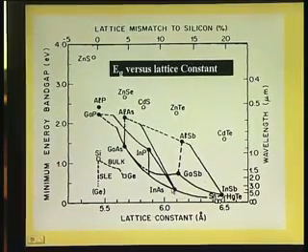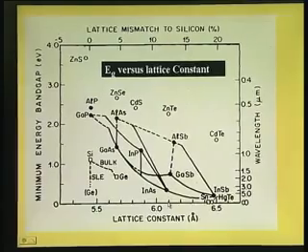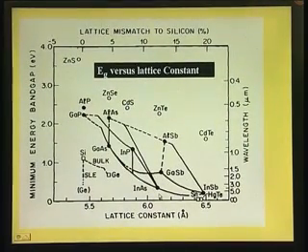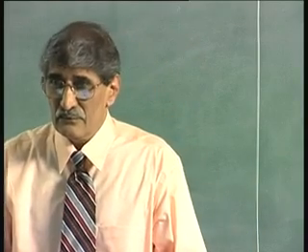It is slightly less than 6.1 angstroms, bigger atom. Indium is bigger compared to gallium. Gallium is 1.26 angstroms, indium is 1.44 angstroms. So that way the lattice constant is bigger.